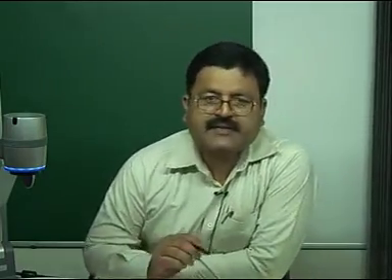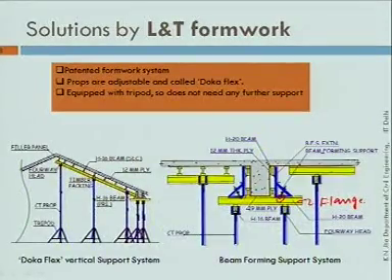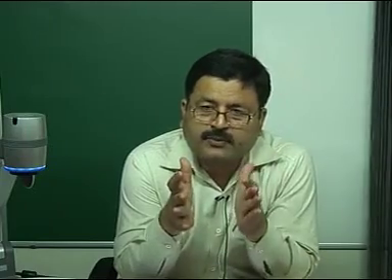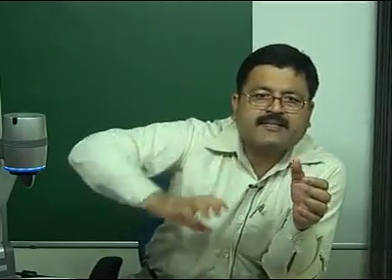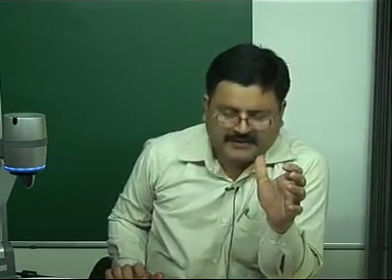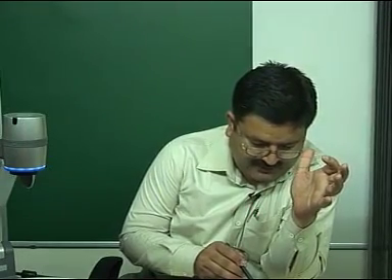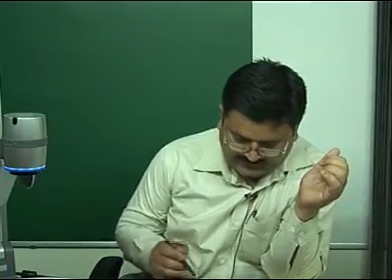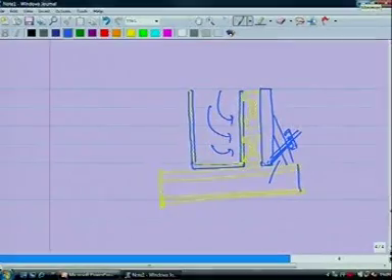Okay, so this is how the arrangement works out, but as I told you, this arrangement is suitable only for smaller beams. If you have higher depth, the pressure would be too much and this clamp and friction arrangement will not work. So for larger depth of beams, you again go with timber. I will show you how. This was for the smaller beam.